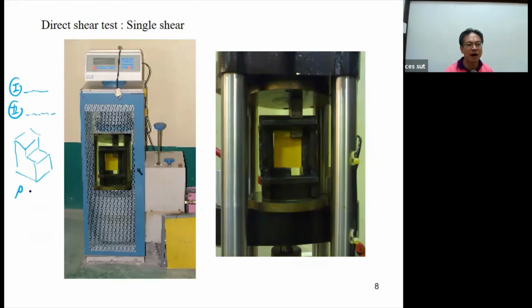And then you find the density by dividing the weight by the volume. Most of the time, the specimen with higher density is supposed to have higher strength, because higher density wood has more grain and can take more loading.